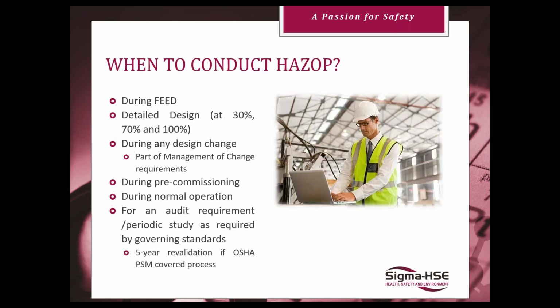Okay. All right. So there are multiple points when you can conduct a HAZOP. During the FEED, you're getting your feet wet, you're deciding what design you want to go with. You can perform a HAZOP and rank the different potential technologies against each other to determine if one has more risk than another, if there's potentially more hazards in operation. Once you've reached a detailed design point, you do a sanity check that your safeguards in place are effective and address the concerns that you've identified.